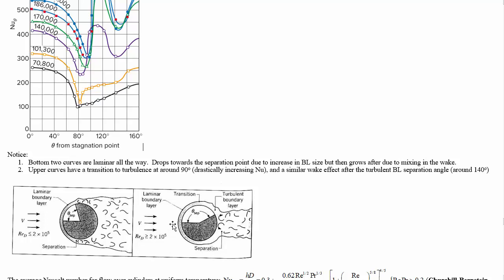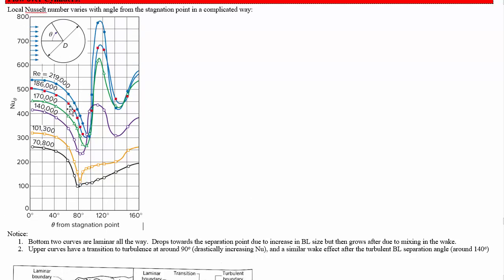Where does turbulence start? Well, it starts once the Reynolds number gets to a high enough amount. So when we looked at the situation for flow earlier, we said that 200,000 was about the transition to turbulent flow. And looking at these are just kind of at the cusp of this transition region of this critical Reynolds number. So below that, you don't necessarily have turbulence, but you can get towards turbulence as you move far enough around the cylinder. So none of these are turbulent at the beginning. They get to turbulence eventually. And where they get to turbulence is where you would have the extra separation point.